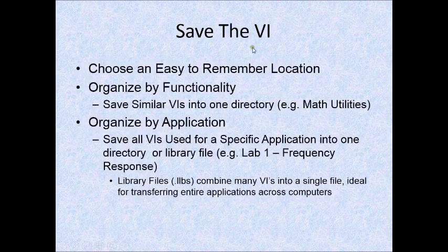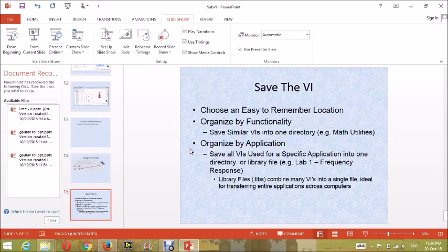To save the VI, choose an easy to remember location. Organize by functionality: save similar VIs into one directory. Organize by application: save all VIs used for a specific application. Now let's come to the main part, let's look at one example. I want to demonstrate.